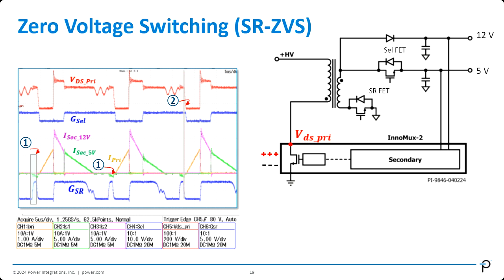You can read it from here, or what we do is that we actually just read it from the secondary side, the drain voltage over here, and get that information calculated inside the IC, and then come up with the accurate and correct number to set the switching cycle to determine how long it needs to be turned on or let the voltage decay. So yeah, it really is reading the information, letting the IC calculate everything, and then just getting the number right.